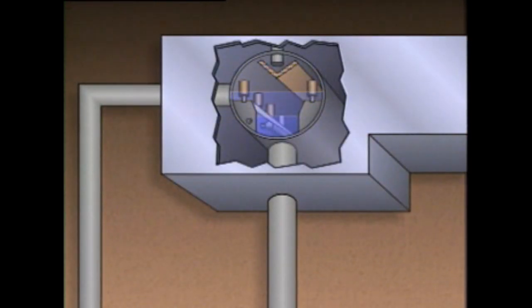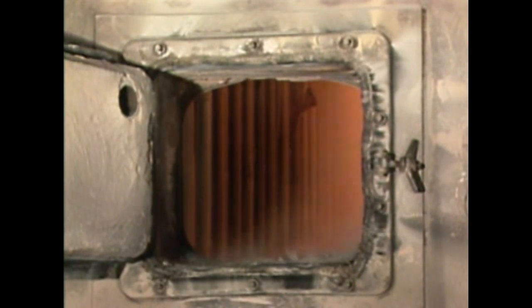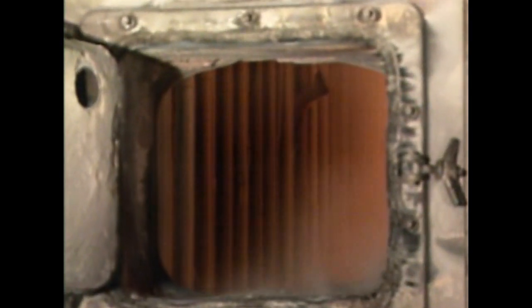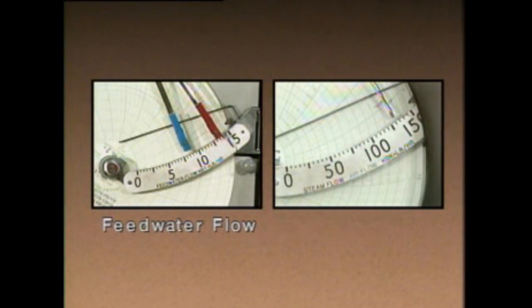As a result, the water level in the boiler drum drops. Boiler tubes are constantly exposed to intense heat in the furnace. In fact, the temperature is so high that it could melt the tubes. The reason the tubes don't melt is that the water and steam flowing through them keep the tubes cool. If feed water flow doesn't keep up with steam flow, water boils off faster than it's replaced. Eventually, there won't be enough water to keep the tubes from overheating and failing.